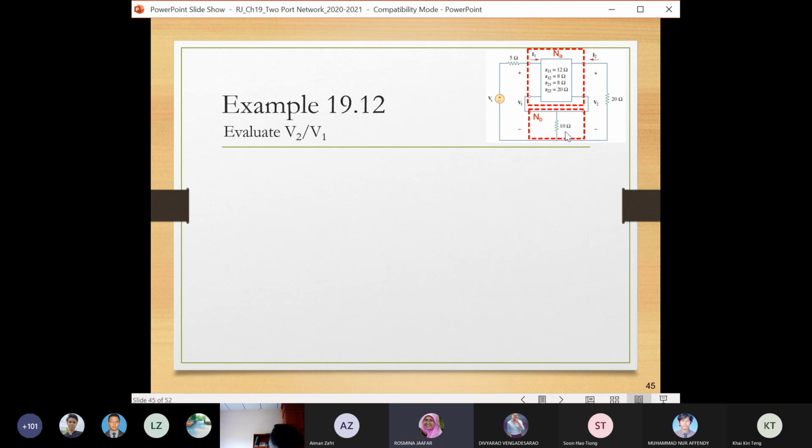Okay, so you have network B consisting of these 10 ohms and the resistance from the top part. It's like a T network on the top. Obviously you can see this because the voltage here is totaled up and the current will flow into the next network. For T networks, we remember the bottom network NB can be represented as a T network. So you have Z12B equals Z21B, and that is the value of the 10 ohm resistor. And Z11B equals Z22B, which is also 10.